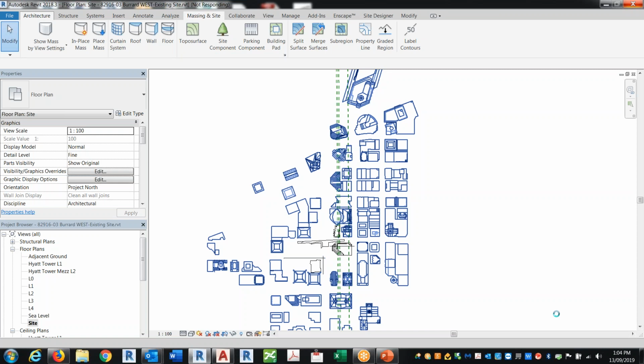Now, guys, if you wonder why CAD import is not a good thing, this is the reason. This is a CAD import. If you build a lot of models, whether it's AutoCAD or another 3D platform, once you put it into the Revit side of things, it becomes really, really bogged down. Heavy? Yes, even though it's very light. This model itself, I did a lot of extrusion using 3D solids, and it's not that bad, but Revit has to do that extra processing in the background. So if you can, build it natively inside Revit so that it's much more manageable, but for this one sometimes you can get hung or something else happens.